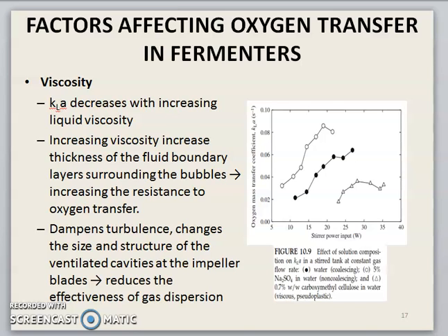It dampens turbulence and changes the size and structure of the ventilated cavities at the impeller blades, which reduces the effectiveness of gas dispersion. Therefore, we need to avoid this increment in viscosity in the fermentation.